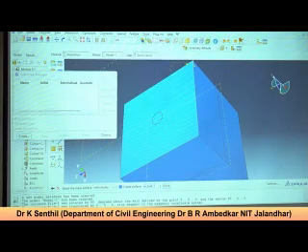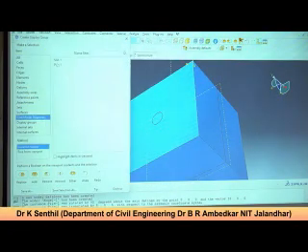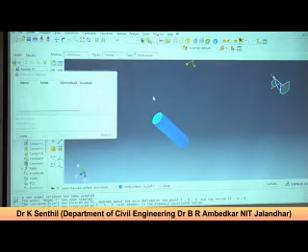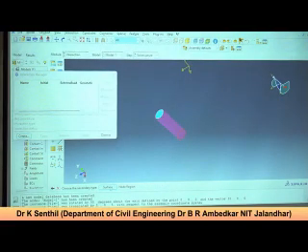So you just go to the tools and display, create, and part module. You just remove the soil, you have the pile, right? Now select the master surface. Yes, that's all. So all the surfaces which are going to be connected with the soil, we have selected. So done. And it should always be surface to surface, because for getting accurate or better results you select surface to surface regions, not node to surface. So node to surface may not give you accurate results.